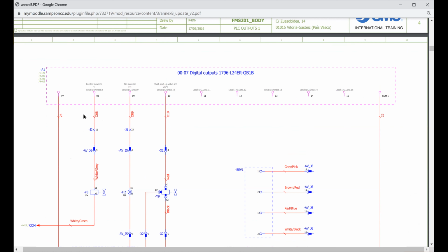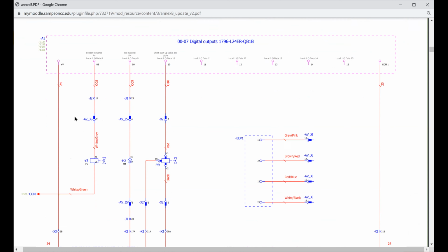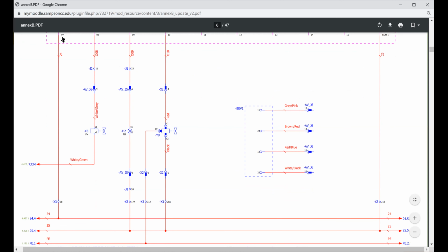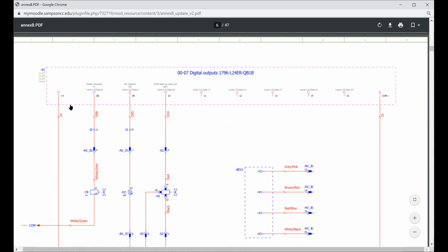That's going to be one of your lights on the panel. Look, there's a 24 volt DC feeding in here. You see that 24? That 24 feeds in from the first page. It goes into the PLC, into an output section. The 24 volt powers all these outputs. It feeds into here. That's your source. And all of these outputs use that 24 that comes into here.